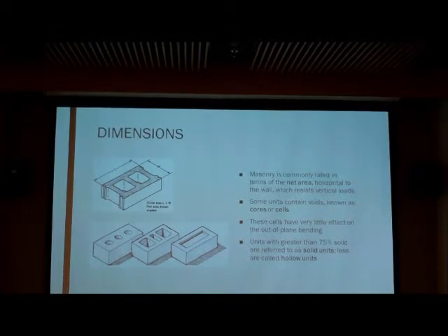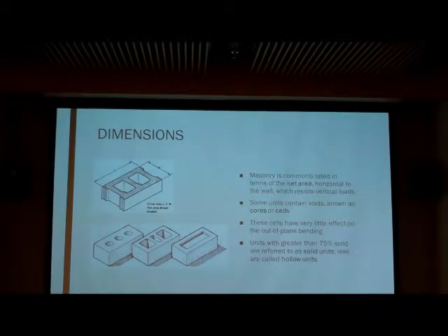One thing that's very important is the net area, because a lot of bricks and other masonry is used for walls. So you mostly need to know its axial area horizontally because that's holding down the compression. So usually the net area is considered the amount of area horizontally that will take force in a wall.